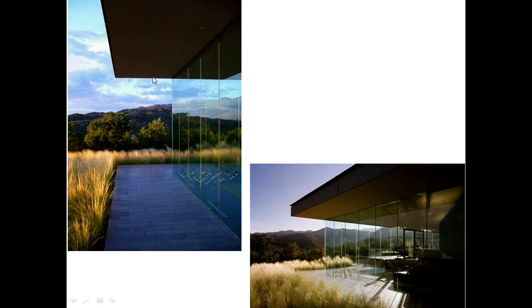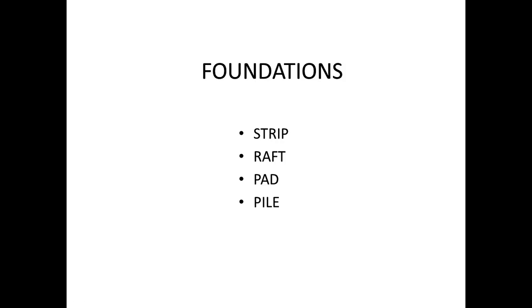So the roof that you're looking at here is being carried on this wall. There are no columns, you can see inside there. There's nothing else going on. The wall is carrying the roof. It's a load-bearing wall. It's a laminate, again. It's a series of layers of glass bonded together to give it thickness and strength. It's been toughened in a very particular way, which again we will go into at some later stage, but there it is. A structural glass load-bearing wall.